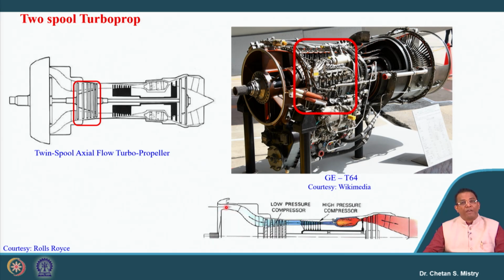So we have the inlet, which is of this shape, from where the flow goes inside. Then, as we have discussed, we will have a rise of pressure. Again it will pass to the HP compressor where we will have a rise of pressure again, and later on we have the combustion chamber followed by the turbine and exhaust nozzle.